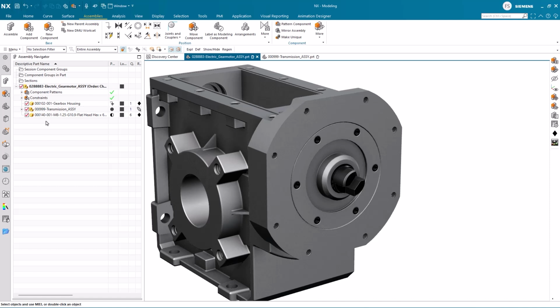We defined constraints to components as we added them, and we noted that the first component we add is generally locked in place by utilizing the fix assembly constraint. In addition, we frequently use the auto align tool. That is a really neat and quick tool when constraining your assembly. The reuse library was used in combination with drag and drop to easily add standard components.